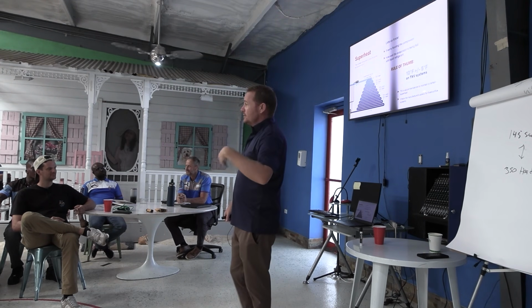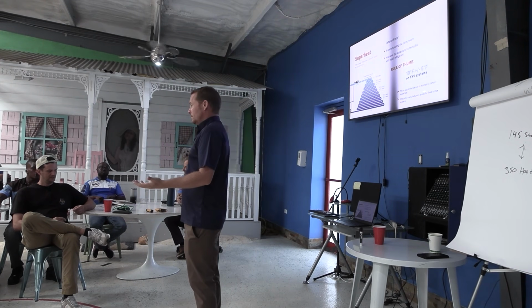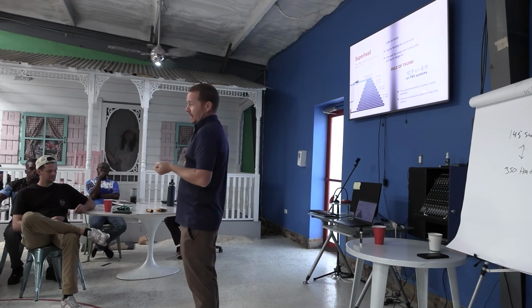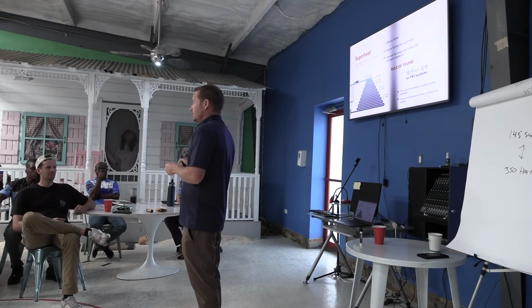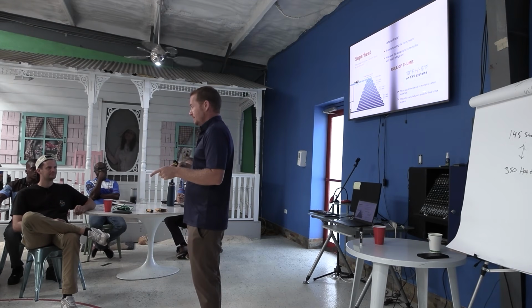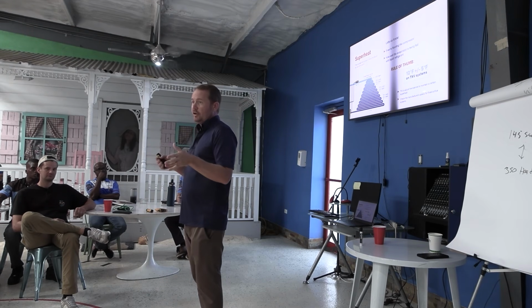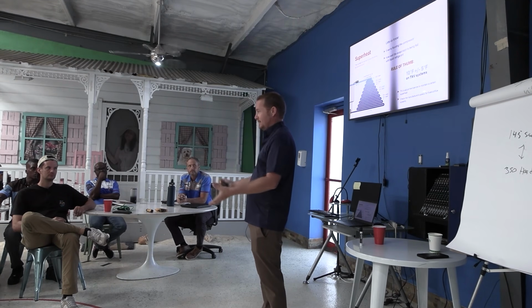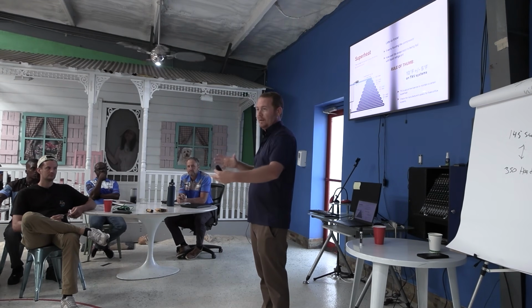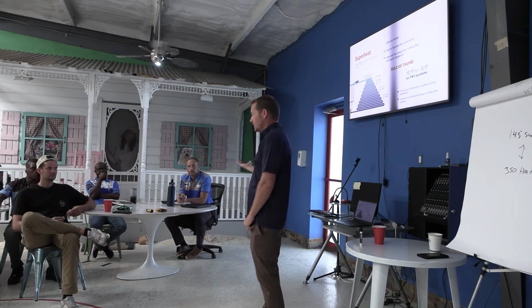So that's not good, but it's also really bad for the compressor, right? The compressor needs cool suction gas coming back to it. So these compressors are cooled by what? Refrigerant vapor, right? They are not air-cooled compressors. You know this because a lot of the compressors that you see, especially on these fancy ones, have jackets all over them. They have a coat on them. And when I first saw that, I was like, oh man, that's going to make the compressor overheat.